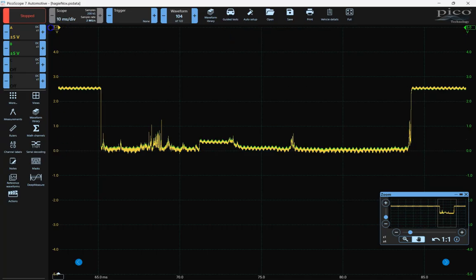If I would have had the failure of a short to ground of CAN low, this would have been a different pattern. So I was able to determine that this is CAN high based on this failure and the history of what I've seen from this before.